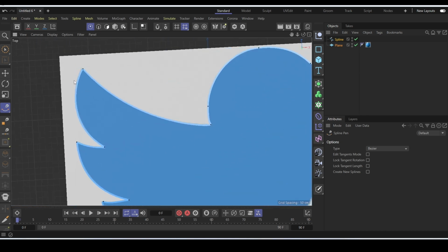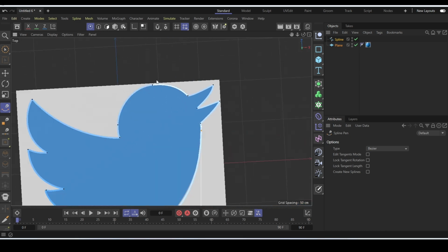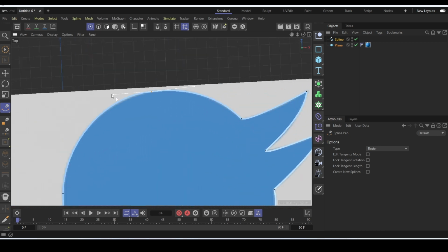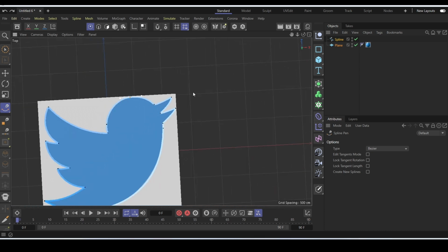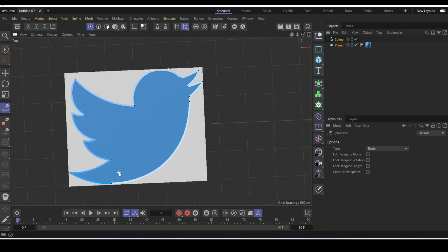Let's say you're not feeling a point, you can always click on that point and adjust it, and even adjust the orientation of each handle. And this is something I feel I should let you know. Once you have pressed Shift to break a handle, like I've done for this one, I can move the handle separately. If you press Shift again to move a handle, it won't work. You have to select it normally because you have already broken the handle. But assuming you have not broken the handle before, you have to press Shift and break it. Why it works like this, I don't know, so I guess we just have to bear with it.